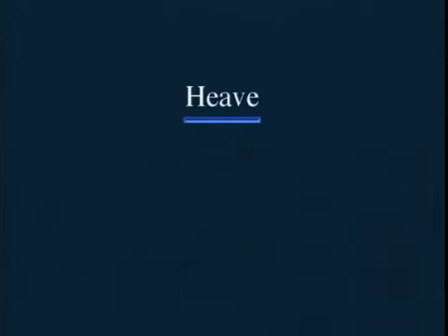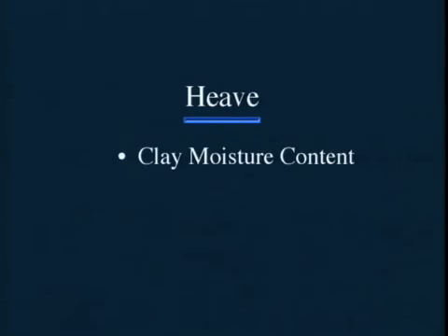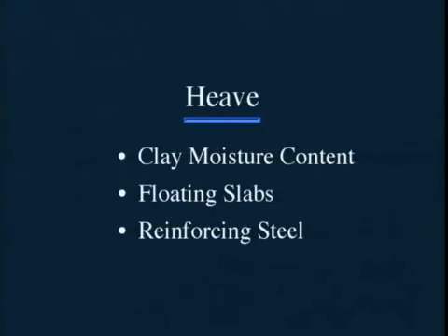Heave is from expansive clays. Under heave, we'll consider the following items: clay moisture content, floating slabs, and reinforcing steel. Clayey soils need to start out in a moist condition that is above the optimum moisture content.